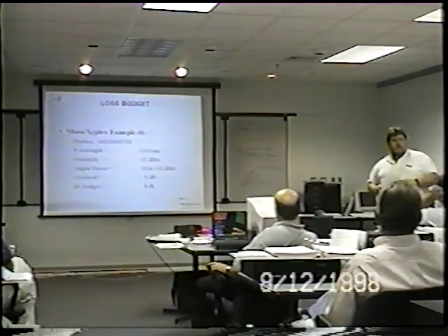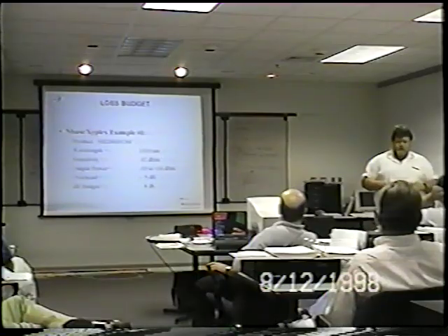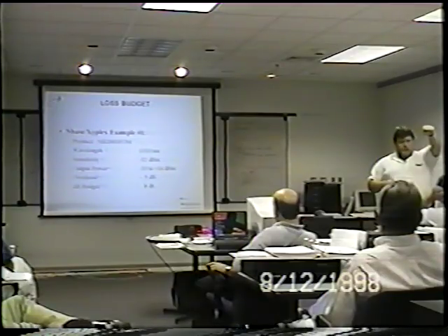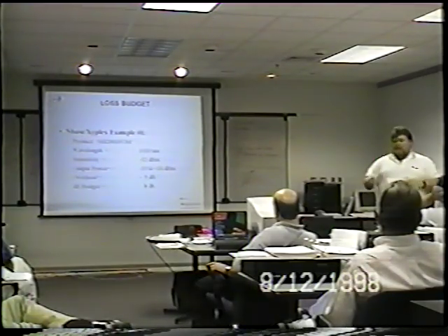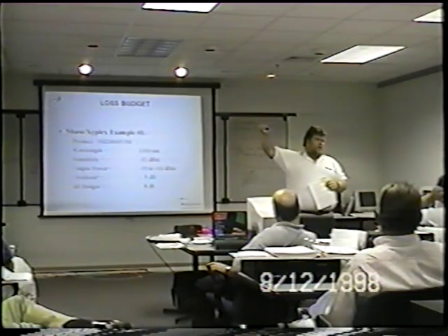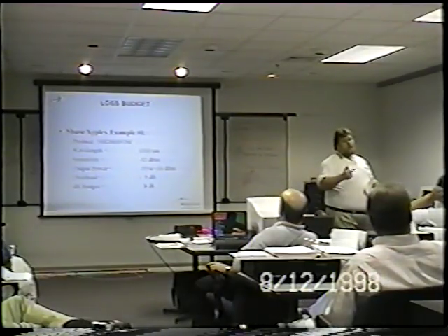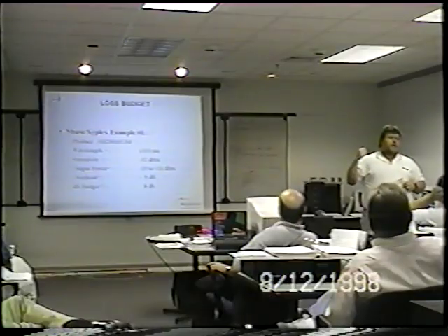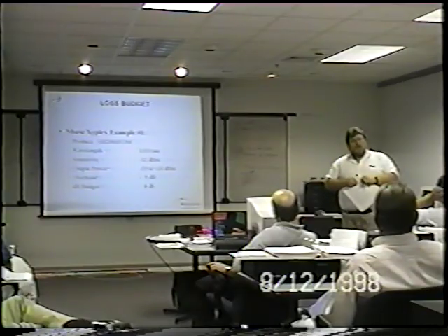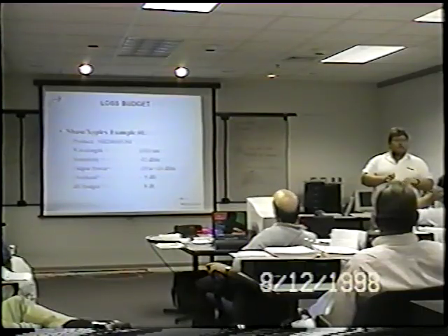In a typical installation, we'll say point-to-point, that's where that 5 dB is derived from. You typically come out of your premises equipment, short jumper cable, hit the panels. That's one set of connections there. Backbone, and we've allowed for maybe another panel before it gets out of the building. So that's another break. Hits the backbone. Is dark fiber going to a central office? The Bell is offering the dark fiber. You might get a couple more panels there. And basically, from that point on, you're looking at a mirror image of that first link. So with those interruptions end to end, you can pretty much chew into that 5 dB fairly easily.